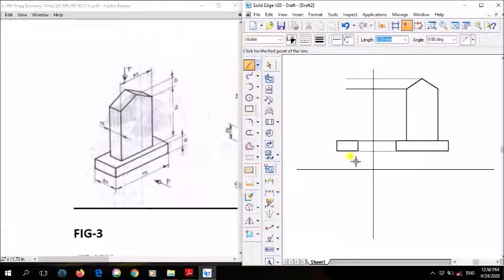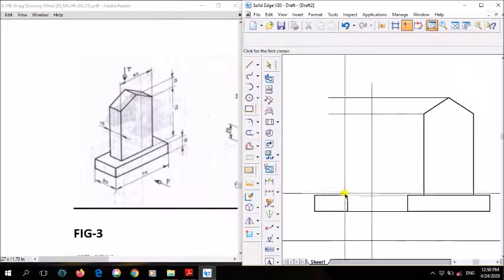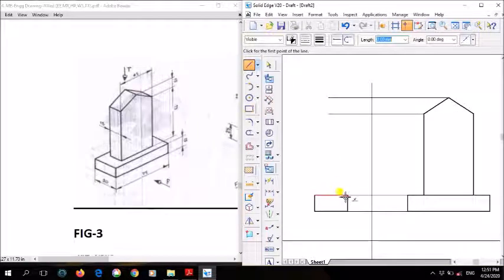So what you do, again same way like earlier. Okay, from this corner here, draw a point of 7.5 mm. So at 7.5 mm here, mark a point. Okay, 7.5. I'll just zoom here. So now what I did is, from this corner, on the left side at 7.5 mm, not centimeter, 7.5 mm, mark a point.